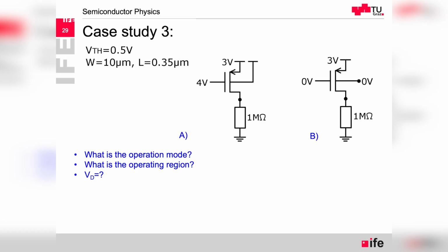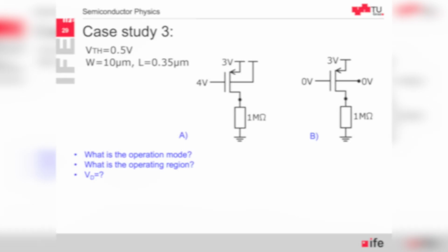So we have an N-type bulk in a p-channel transistor, and then p regions at the drain and source. So when p is higher than N, we have forward bias. And whatever we apply at the gate, we mainly see the current that goes between the source and the bulk.